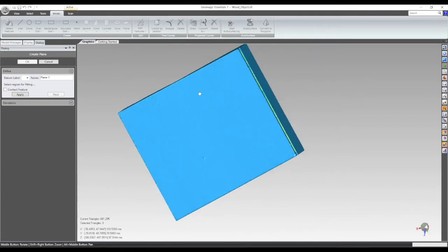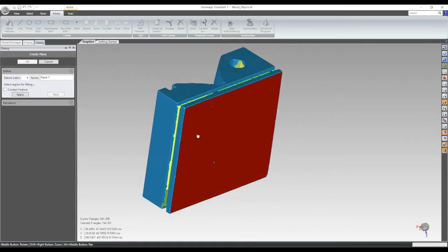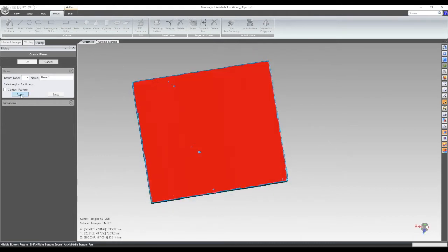and for example we want to have a plane with all the area, we can choose over here the right angle tool, for example, and could mark all the area with the control button and left mouse button; again, you deselect. A very nice and fast function for flat areas is to switch on the select by angle mode, choose a brush and just click on the object, and then everything that is connected to the flat surface is selected by the software automatically. So we click on apply,